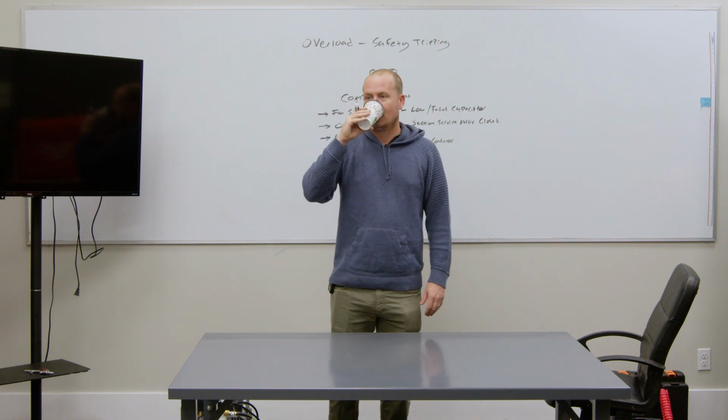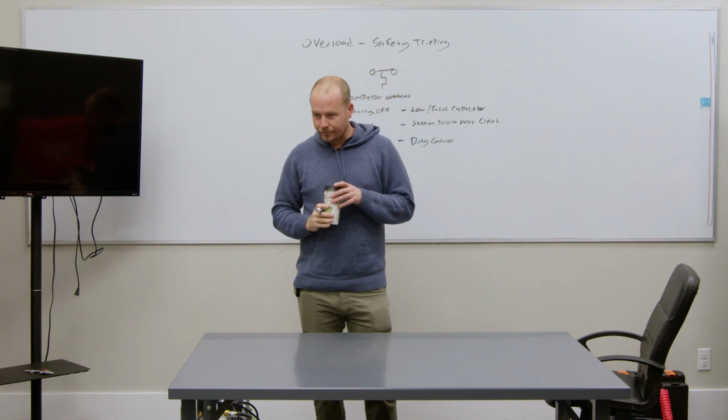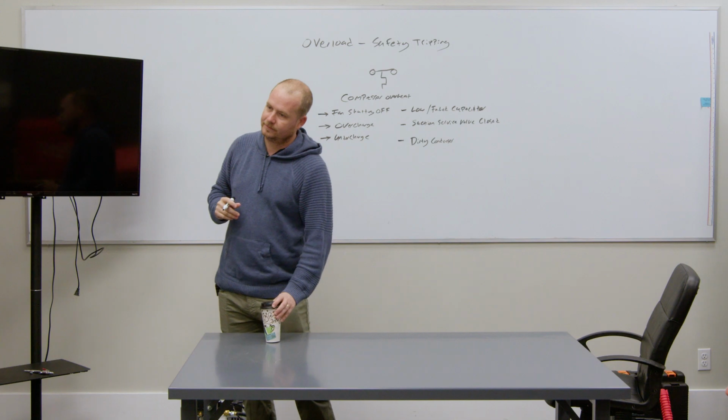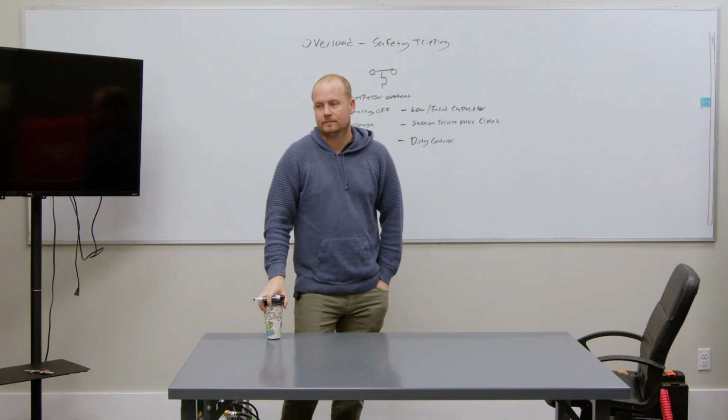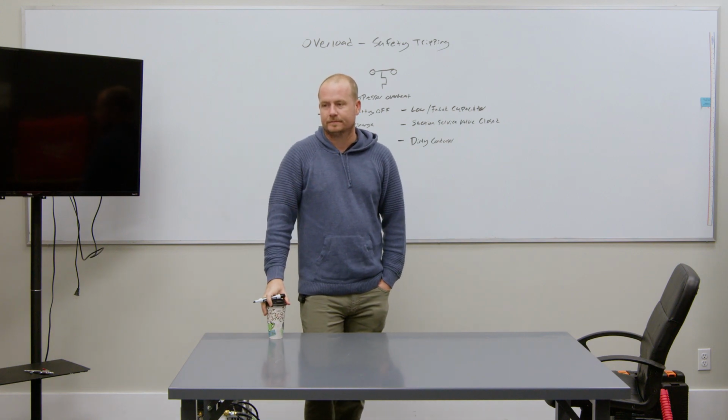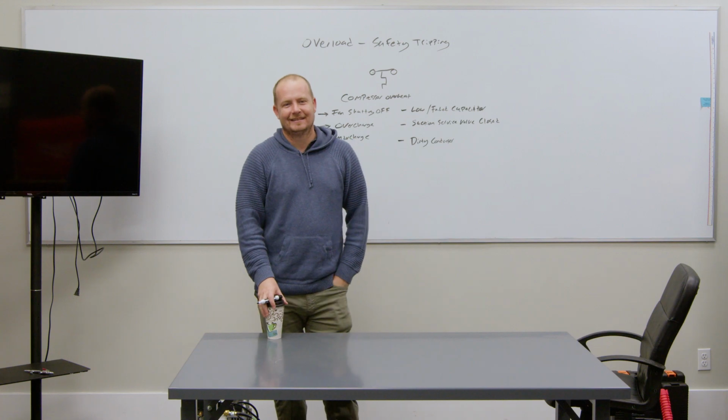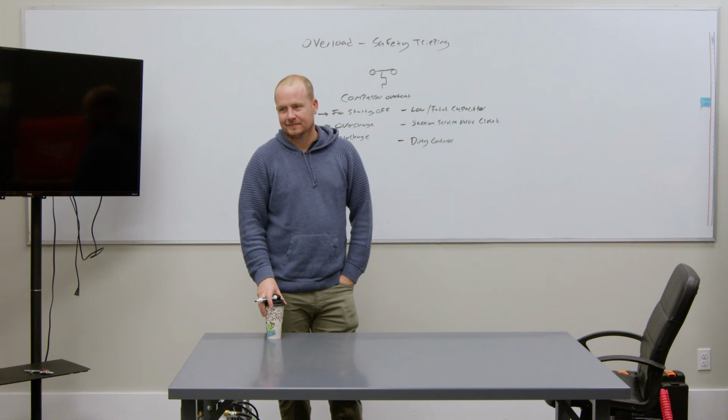You know, intermittent fan issues, and it would trip the high pressure switch, and then it would be on lockout. But you wouldn't find the compressor overheated, because of the safety. Good point. That was high pressure switch. I'm getting ahead of myself. People were always confused because the LEDs were backwards. That is annoying too. So instead of it showing high pressure, it showed low pressure.